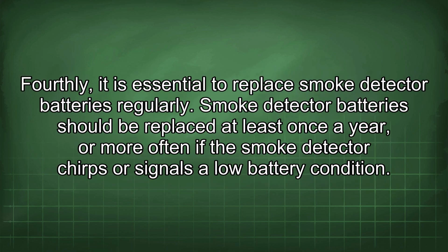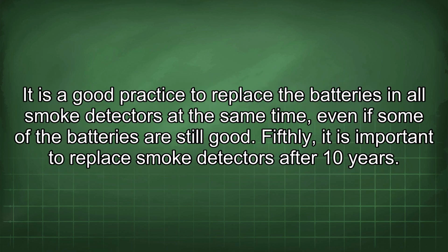Fourthly, it is essential to replace smoke detector batteries regularly. Smoke detector batteries should be replaced at least once a year, or more often if the smoke detector chirps or signals a low battery condition. It is a good practice to replace the batteries in all smoke detectors at the same time, even if some of the batteries are still good.